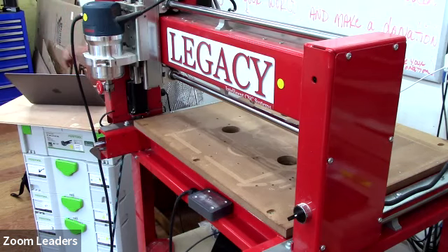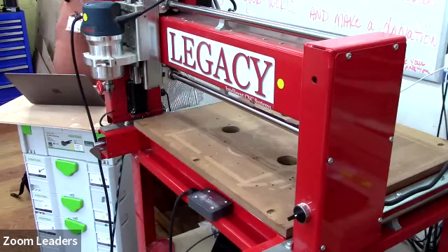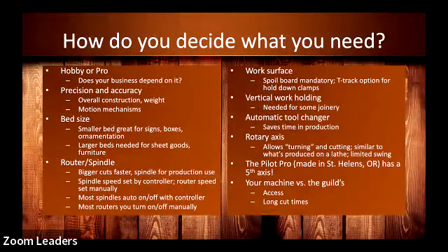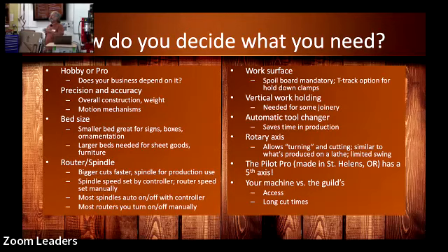If you're way on the high end in terms of production, as we mentioned, a number of projects will require multiple tool paths and multiple tool bits. We have to take out a wrench, and you know how it is to change a bit, collets and all that stuff in your router. You're going to have to do that on a machine like this, unless you get one of the fancy automatic tool changers where you lay out a half a dozen bits and the machine just goes over and drops off the old one and picks up the new one and automatically aligns it and positions itself so it knows where it is and off it goes by itself. If any of you get that machine, invite us all over to use it.